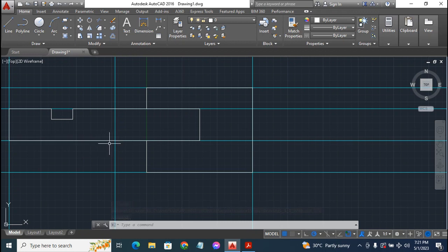So you also agree with me that between this horizontal line of this third rectangle and this vertical construction line is also 90 degrees. But what we need here is 60 degrees. So you take away 60 degrees from 90 degrees, what will be left? 30 degrees. Yes, 30 degrees. So that means the base of this third rectangle should be inclined at an angle of 30 degrees in order to get the 60 degrees that is required here. Okay, so we'll rotate this third rectangle at an angle of 30 degrees.